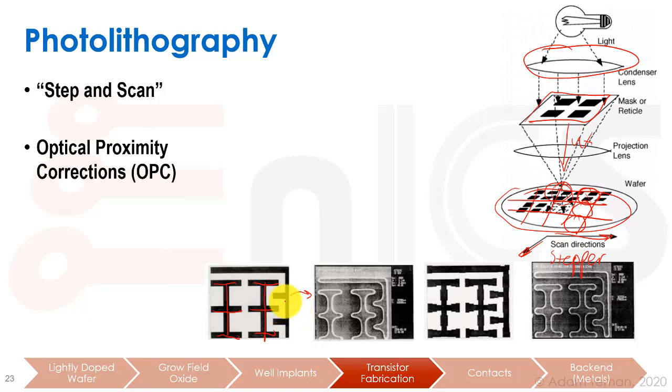So when we send our mask set out for fabrication, what is done is that we run these optical proximity corrections on the mask, and they find out how the light's going to actually refract, and if they should add all kinds of little features, like as you can see here, these little handles are added, and when you shine the light through that, you get something that's much closer to what we actually intended at the beginning. So this is something that's done after we tape out our chip, before the masks are made.